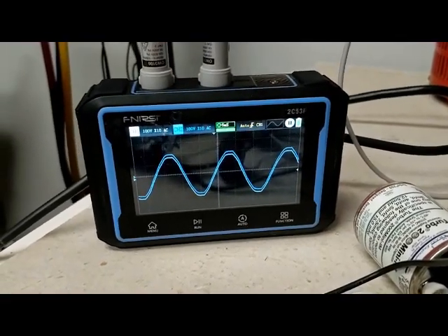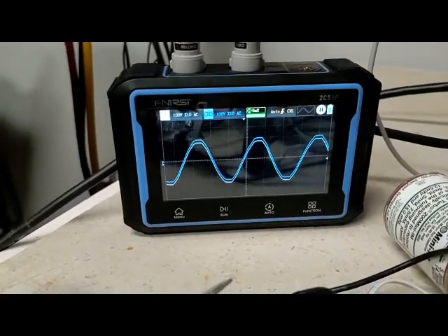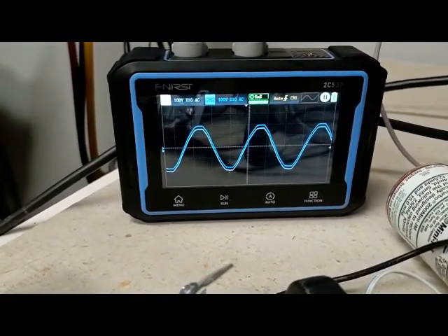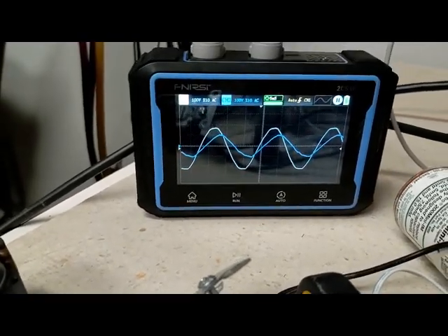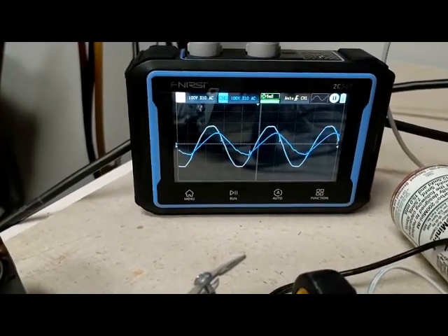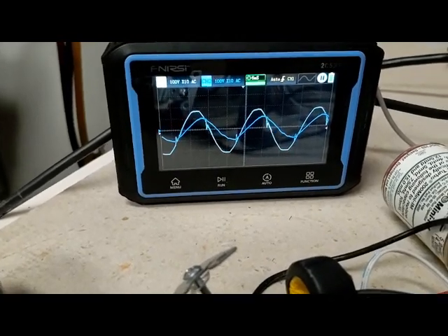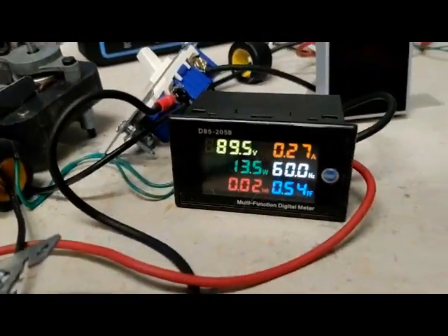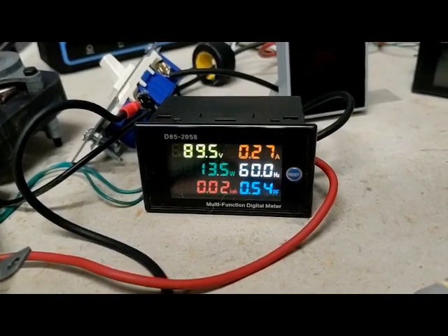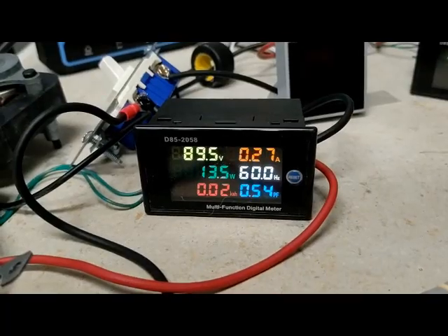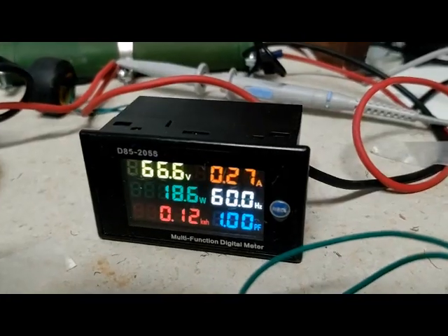The dark blue line is the voltage across the resistor, and the light blue line is the voltage going into the circuit. When I add inductive reactance by turning the motor back into the circuit, the voltage across the resistor now peaks behind the voltage to the overall circuit. That indicates that the circuit current lags the circuit voltage. And now you see the motor's getting 89 volts, and it has a power factor of just barely over a half. The resistor, meanwhile, still has a power factor of 1.